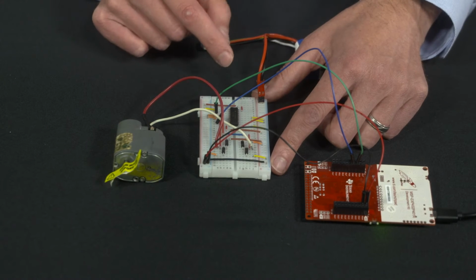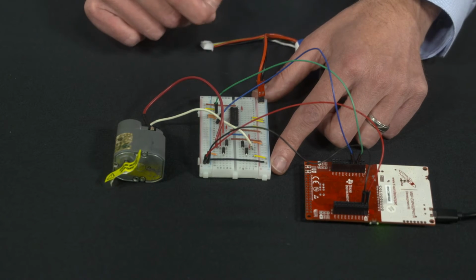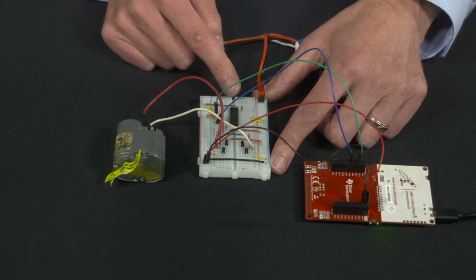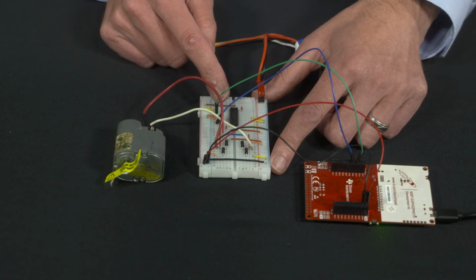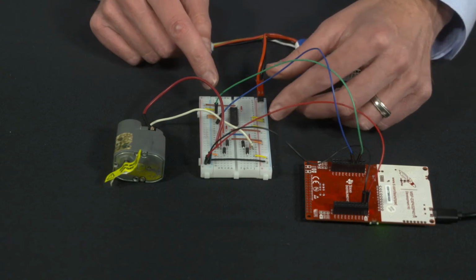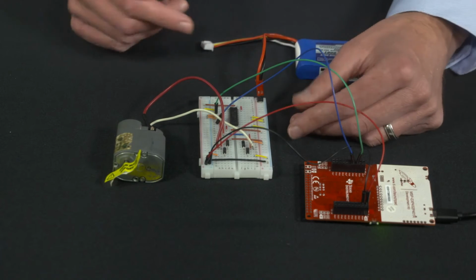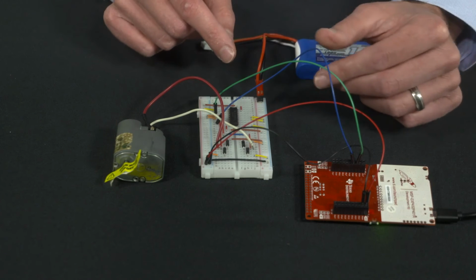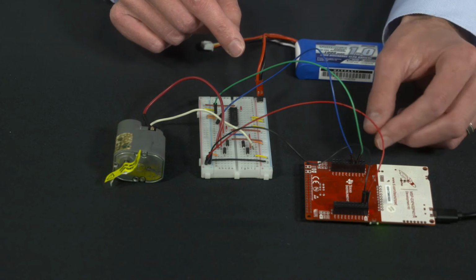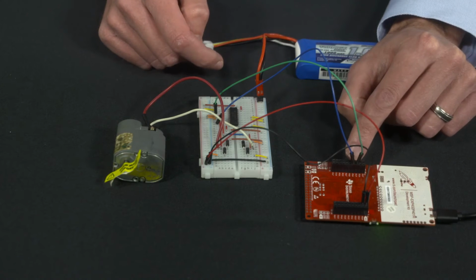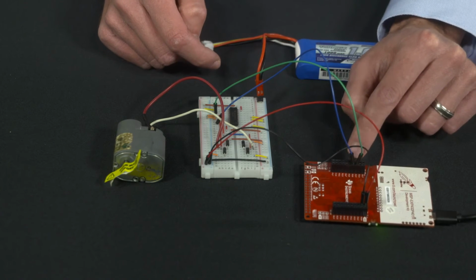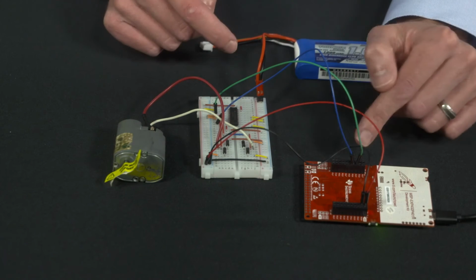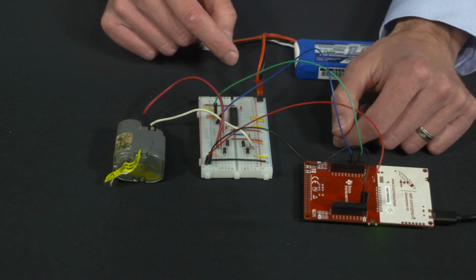Now driving the H-bridge, we need 2 digital logic inputs. One input, when that input goes high, it's going to turn one direction, and then another digital logic input where when that input goes high, it turns the other direction. So these 2 digital logic inputs are essentially the direction pins. And you can see for this H-bridge setup, those 2 pins are driven by the blue and green wires, which go right to general purpose input-output digital logic pins on our microcontroller. So we're going to drive the direction of this motor from these 2 digital logic pins.